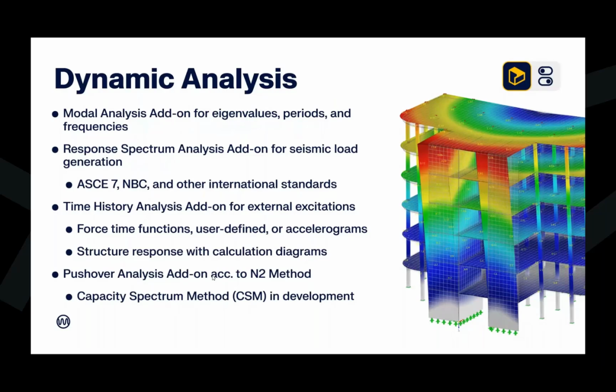We have our third dynamic add-on, the time history analysis, and this is for external excitation. So we have the ability here to define this force time function, or it can be user defined, or we can choose from an accelerogram library if we would like to replicate this seismic load on our structure. And once we've carried out this time history analysis, we can view the structure response with what we call these calculation diagrams. And I'll go ahead and jump to the next slide quickly just to take a look at this.